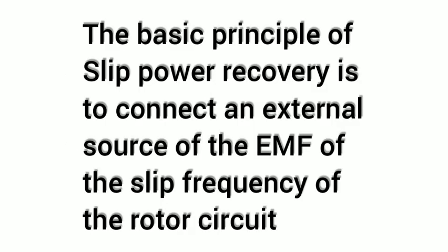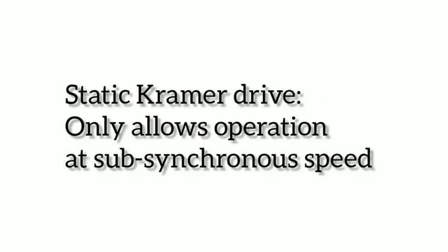Today I am going to speak about the topic of slip power recovery schemes for induction motor. Now I am going to say about the basic principle of slip power recovery. The basic principle of slip power recovery is to connect an external source of EMF of the slip frequency to the rotor circuit. Now I am going to explain about the static Kramer drive.